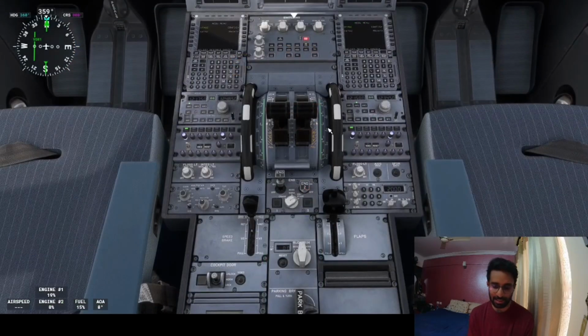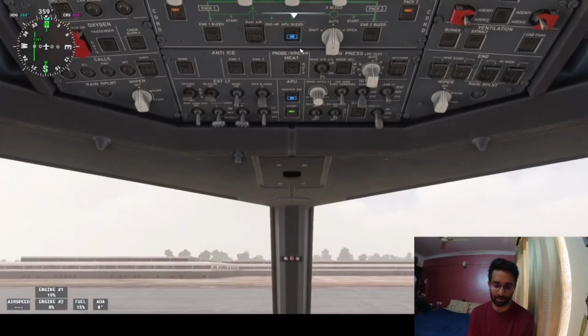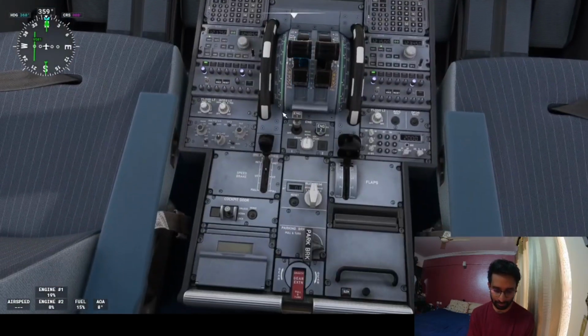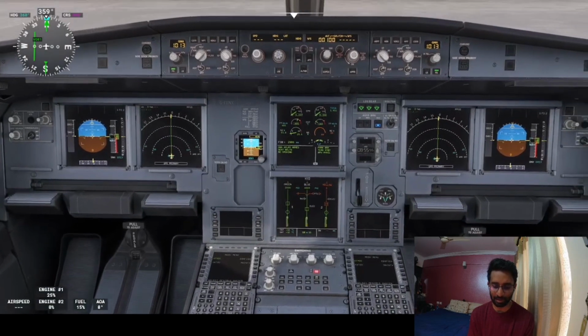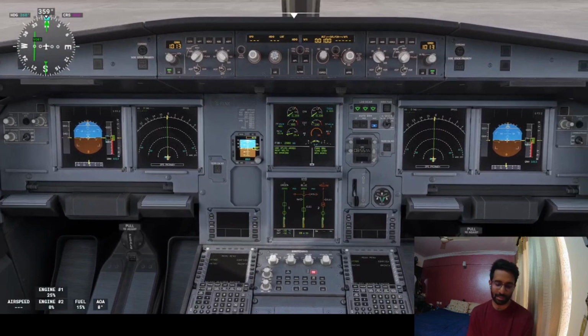The single engine taxi procedure says that your first engine is started. These are all single engine procedures, you can disregard all these things. So now what happened? Say the nose wheel steering is not connected. He has left. Pushback is completed, so the parking brakes are set. One engine has started. Blue automatically starts after the first engine is started.